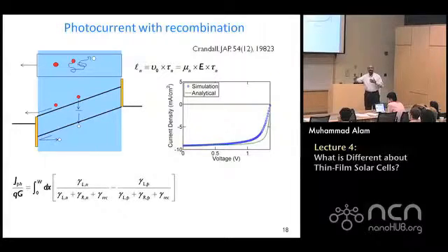And it's going to stay alive for tau. So that is the distance over which it is going to recombine. And if it recombines and doesn't come out, it is as if it were never generated, right? Because I do not really know whether it was generated and then recombined, or essentially was not generated to begin with.